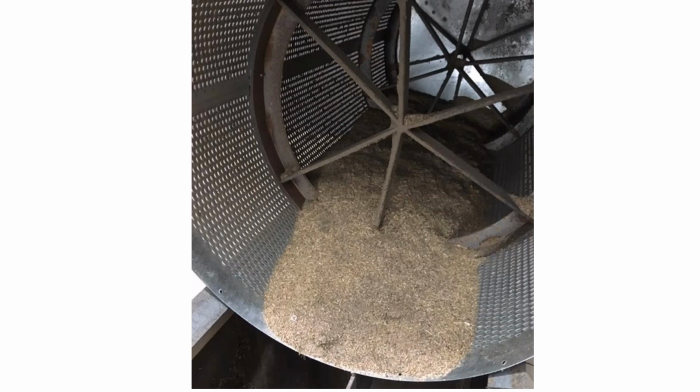Here's an example of how the effective louvered area of a simple aeration tube is sometimes not what it appears. One of the downfalls with the simple aeration tube is that they aren't self-cleaning. So ultimately, the chaff will build up over time, and you will lose effective area. You can see in this example, you probably have at least a 10% reduction in louvered area, and that is going to happen over time.